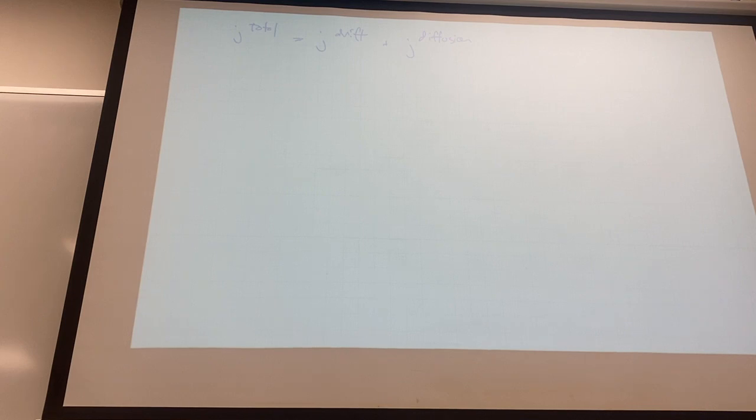We'll illustrate a lot of this stuff later on, but developing the intuition is maybe the hardest part of this class: what happens when you bring a p and n-type device together. Think of it happening live as you bring the two together. Where do the charges flow? Where are the fixed charges? Where are the mobile charges? How does it end up resting at steady state? You figure that out, then we're going to mess with it by applying external fields and flowing current through. Other things happen. But if you can figure out how the system starts, then you'll be in a good place to figure out how the system changes when we add external interference, basically.